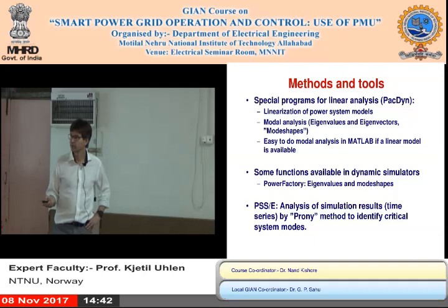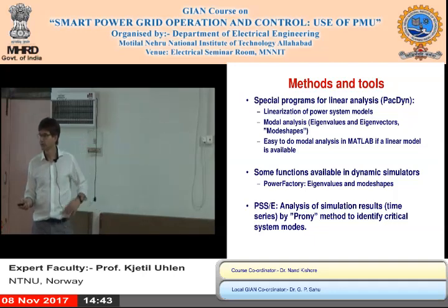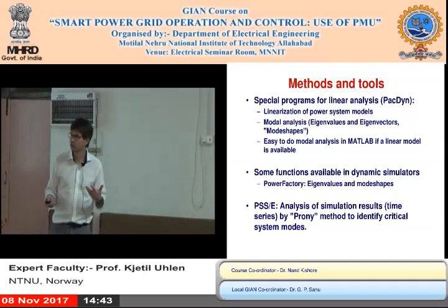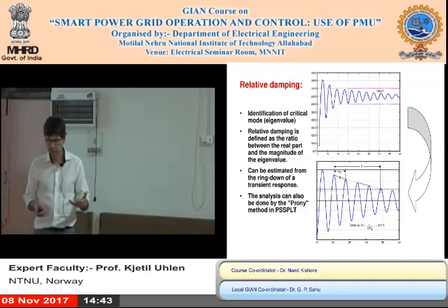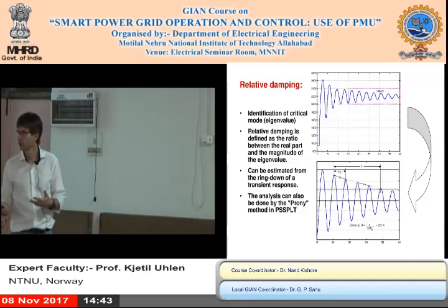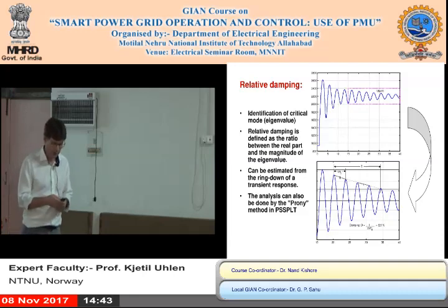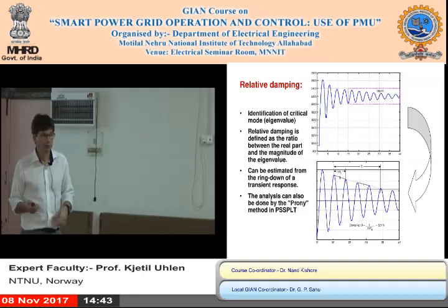PowerFactory has a fairly good tool for small signal analysis. So I can demonstrate that later. In PSS/E, there are some methods available, but you could also use other methods, such as the Prony method, to identify critical modes. An example of a Prony analysis is here. And I'll also come back to Prony analysis later when we talk about PMU applications.